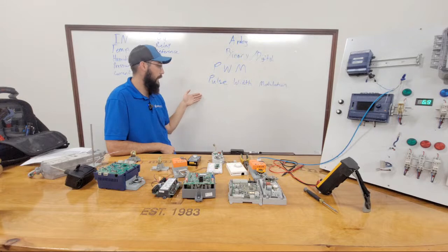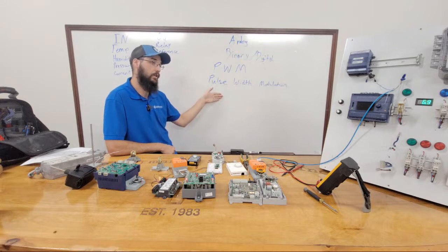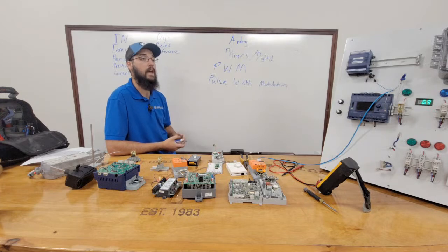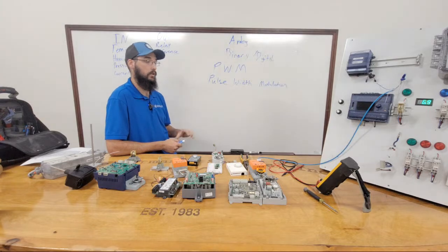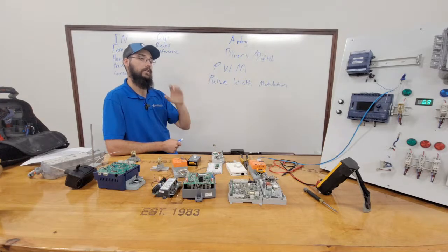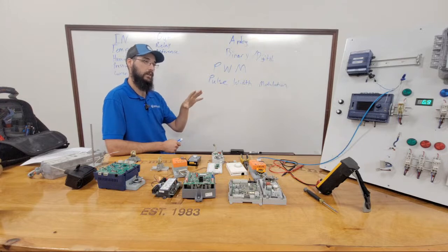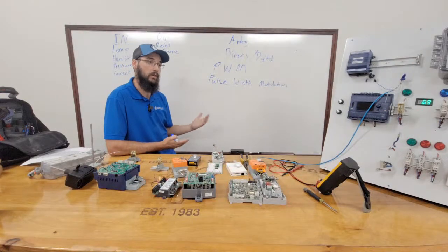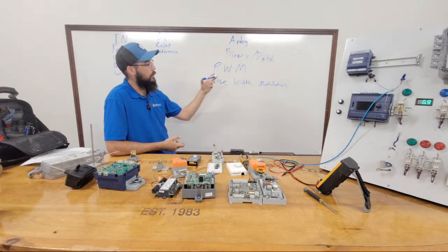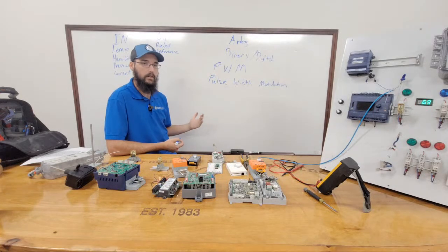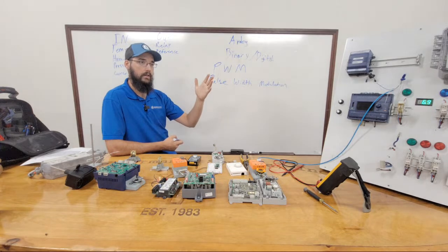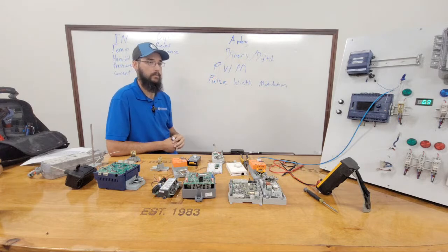So you could have an input reference that's pulse width modulation going into that controller, telling it, okay, I want you to run at 50%. So the pulse width is going to send a signal by sending pulses, and it's quite literally just that. It's a pulsing of the signal to generate a set outcome. You know, we want this to happen. So in the same way, that SCR heater is pulsing the voltage going through it to achieve the same result.